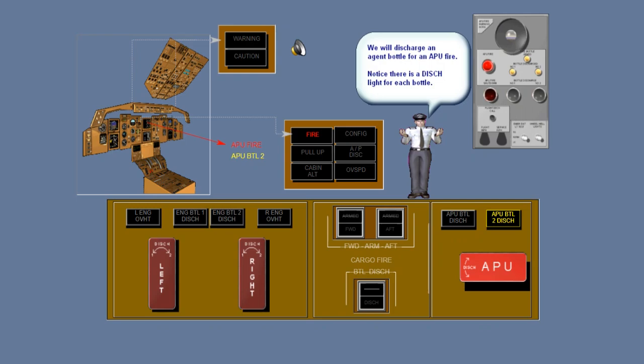Some aircraft have the following option. On the ground, with engines off, the system operates with OR logic instead of AND logic. In this case, a detected fire by either loop will activate the fire warning. If an APU fire is detected, the APU automatically shuts down.